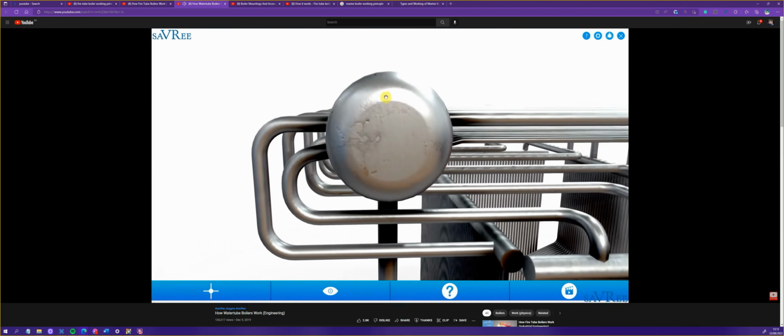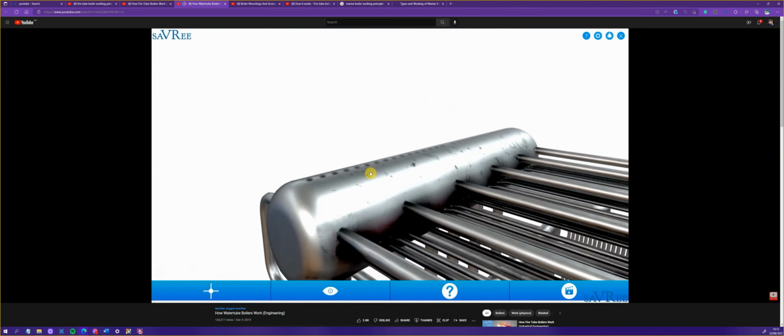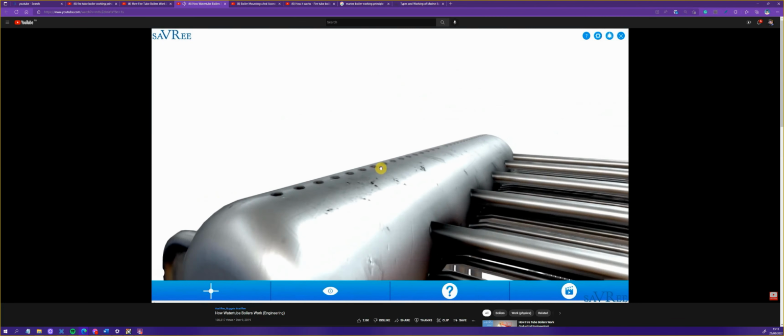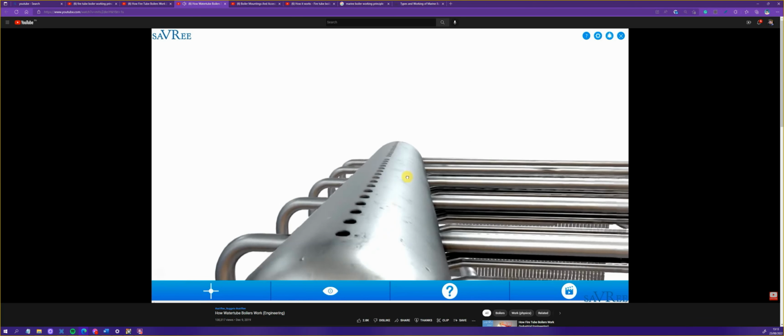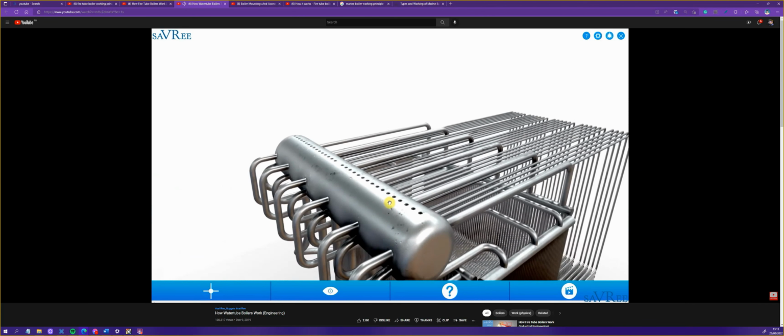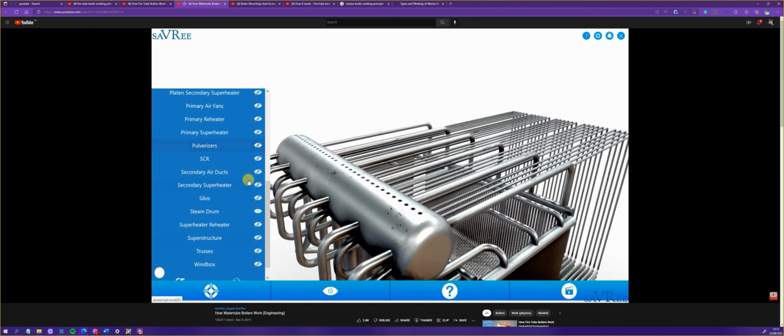In our steam drum, we're going to use baffle plates, scrubbers, and maybe steam cyclones to separate some of that moisture from the steam. The moisture or water drops that get separated can then be recirculated in the boiler, but the steam we get out of our steam drum should now be quite dry. It should be saturated dry steam. So let's just add our steam pipes out, and in order to do that we've got to figure out where we're going next. And where we're going to is our primary superheater.